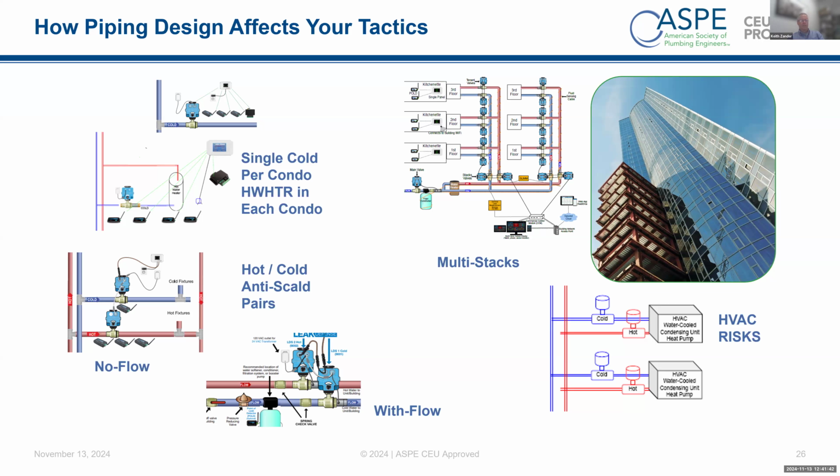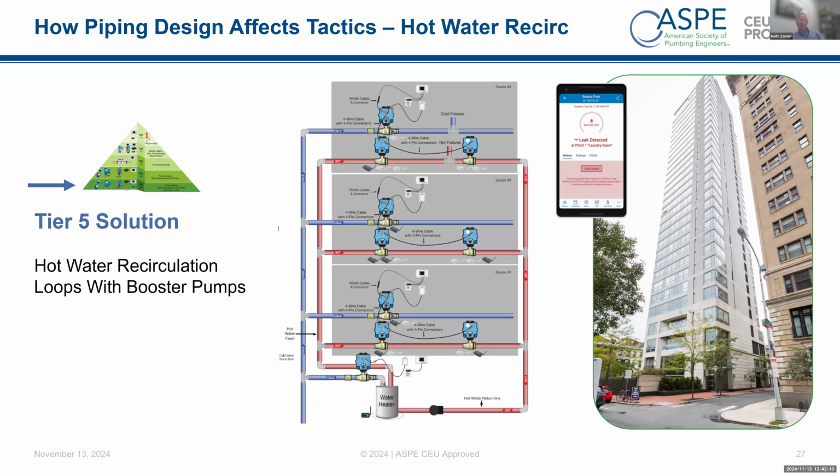Okay, we've got a water restriction here. What's the easiest way to solve our water restriction problem? Make your people use less water. How do I do that? You bill them for it. Well, in order to bill them for it, the piping's got to be configured so you can bill them for it. Stacks and risers going straight up the center of all the multifamilies are not going to be conducive to billing each of the tenants for whatever water they use. So obviously, there are guys that are bad stewards of the water. You don't want the guys that are good stewards of the water paying for the bad guys. So your piping arrangement is going to really depend on everything.